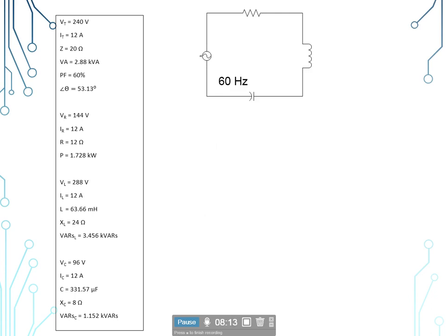Here are all the numbers that we calculated. We have a list of it. Now we're ready to go out to a live circuit with our meter and make live readings so that we can compare to this. Are we close? Go look somewhere else. Are we way off? Better look at that part of the circuit a little bit closer. There is an issue there.